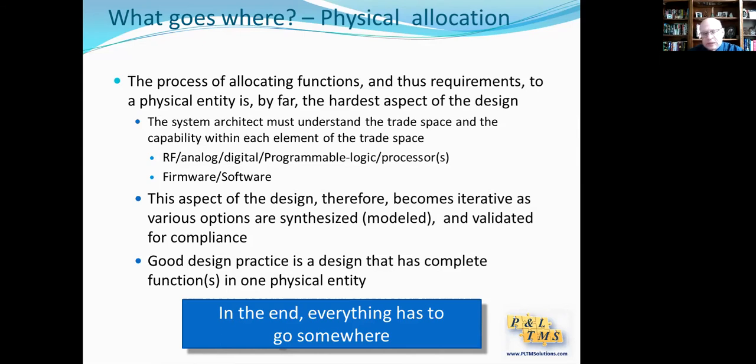And certainly in today's modular world, where you're thinking to have common modules and then you integrate them together and you get a different type of system, a tight physical and functional partition is very important. But if you work in an unmanned air vehicle and size, weight, and power is everything, I tell you, you find yourself using every square inch of that board because you don't want to add another board, right? And so maybe the physical and functional partition is not that tightly coupled.